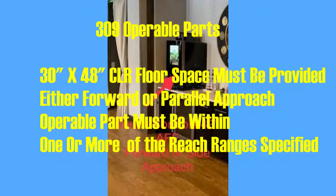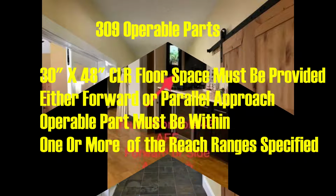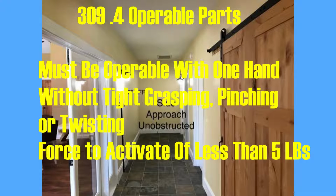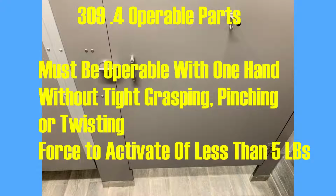Section 309, Operable Parts. A 30-inch by 48-inch clear floor space must be provided either for a forward approach or a parallel approach to the element. Operable parts must be within one or more of the reach ranges specified. An operable part must be operable with one hand. It cannot require tight grasping, pinching, or twisting. The force to activate the operable part must be less than 5 pounds.